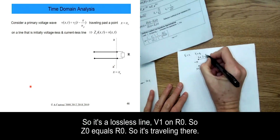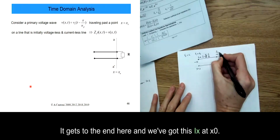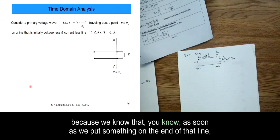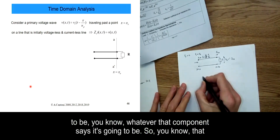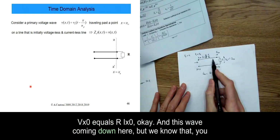Say it's a lossless line, V1 on R0, so Z0 equals R0. The wave travels down to the end, where we have Ix at x0. The relationship between Vx0 and Ix0 is determined by the component R, because as soon as we put something on the end of that line, it has a VI relationship that is forced to be whatever that component says. So Vx0 equals R Ix0.